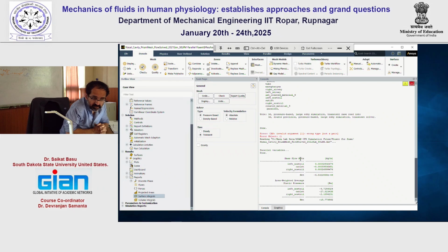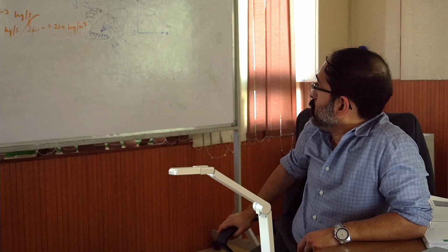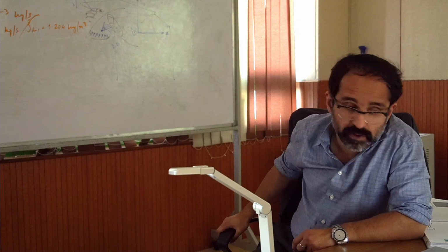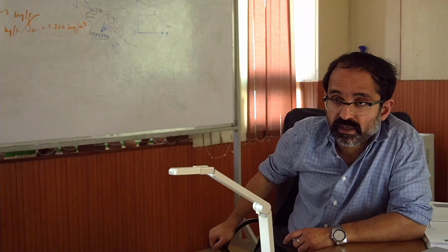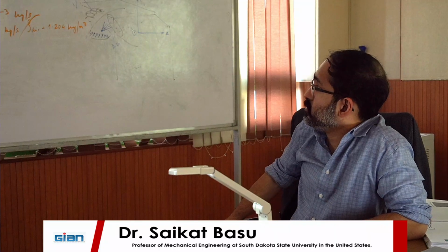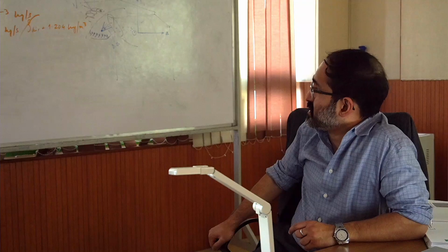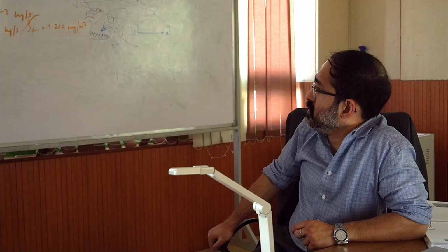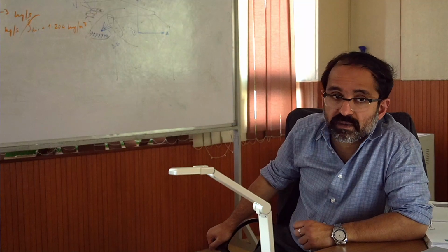Yeah. So in the next session, we are going to first show how to figure out the location of the nozzle if you have a nasal spray, and for that we have to go back to ICEM for a brief while. After that we are going to come back to the Fluent world and set up the particle tracking, run some quick particle tracking simulations, get the data, and for that you guys have to do some calculations on some of the printed sheets, and then we are going to compare that with some published paper. I think we can get it done in 1.5 hours, but maybe comparing with the published paper could happen in the last session.